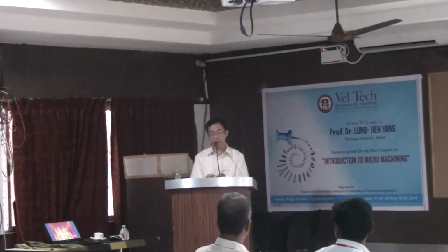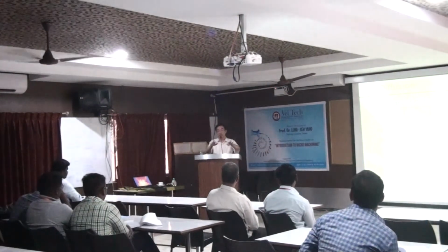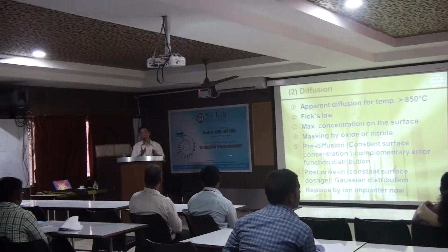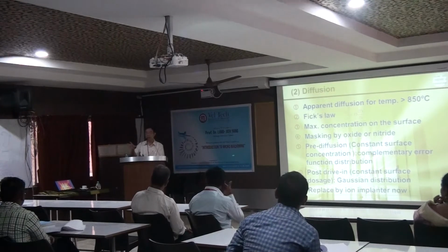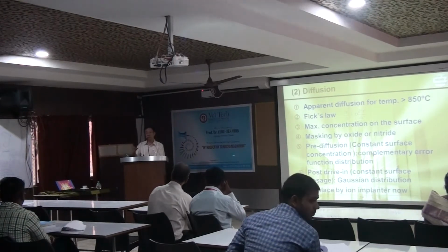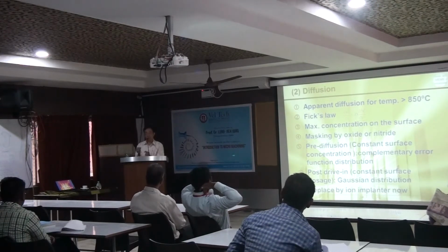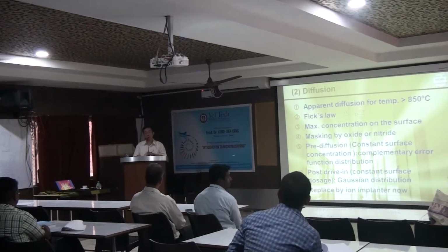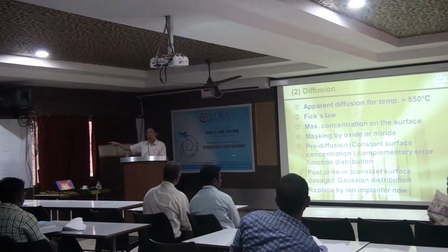But very similar to some material process, we call it anneal. Anneal is something that we do when we have some damage in our structure. So we put it in a high temperature furnace, holding it there, just feeding in some nitrogen gas inside to prevent oxidation, and holding for a long time. So the microstructure can try to restore, right? They can fix and restore to their original state. Something like that is what we call anneal.